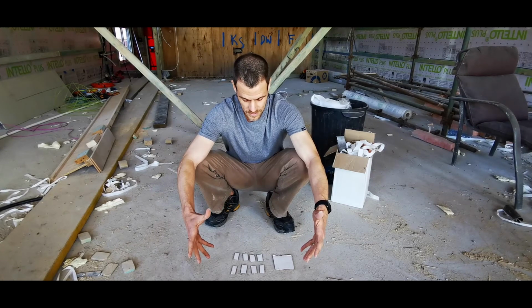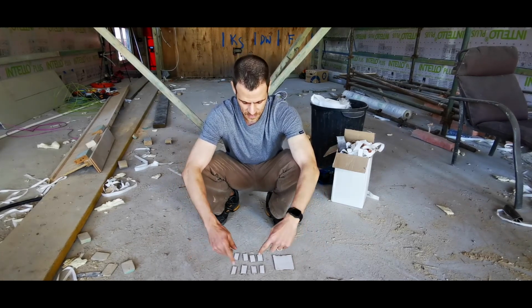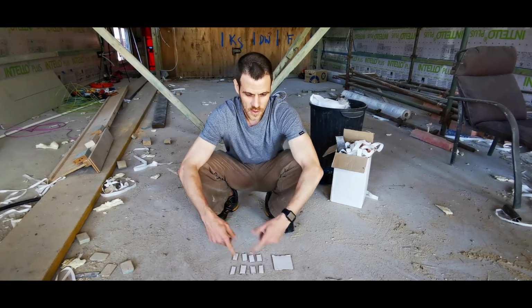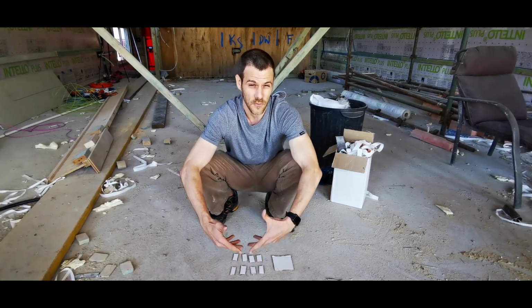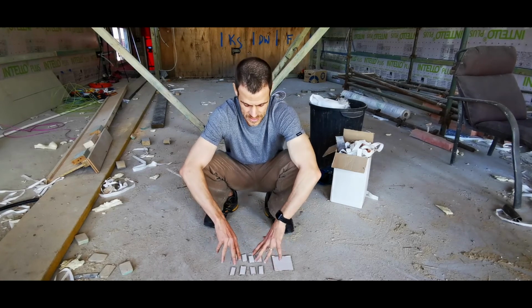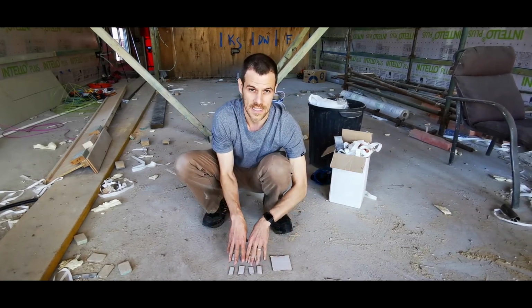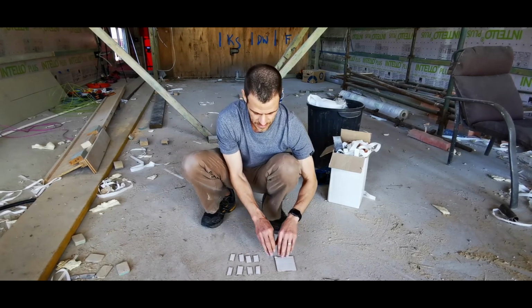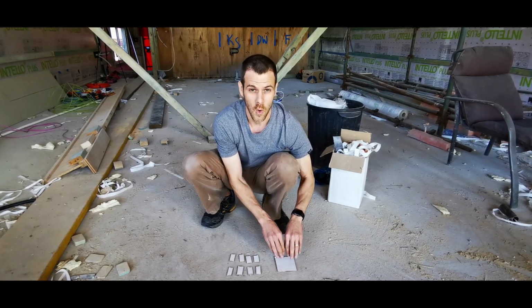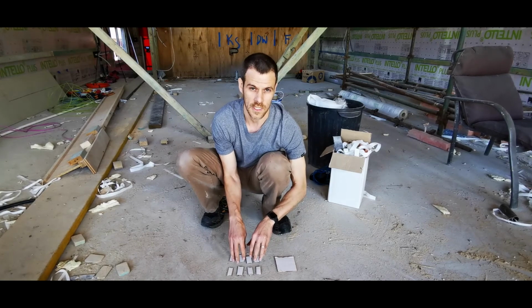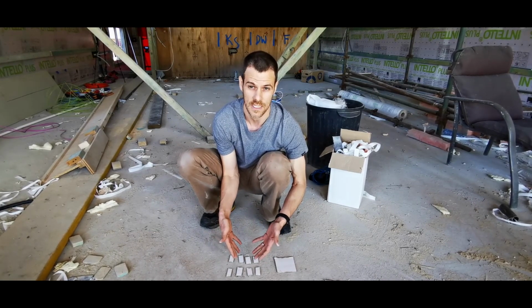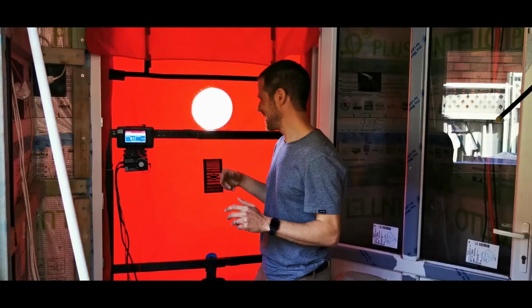Because of fluid dynamics, there's a lot of air turbulence going through these smaller holes, and the turbulence creates friction, and that reduces airflow. So even though the collection of these is the same size as this single leak, the single leak will leak more than the collection of smaller leaks, because there's more resistance through many smaller leaks than through one big leak.